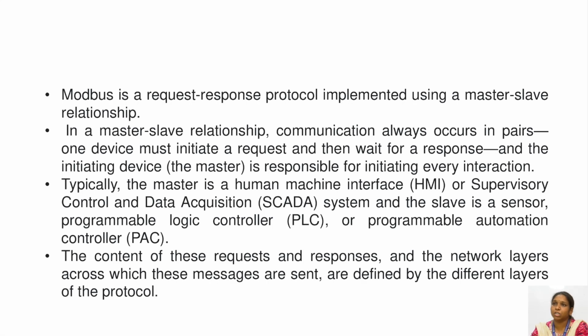Modbus is a request-response protocol implemented using a master-slave relationship. In a master-slave relationship, communication always occurs in pairs. One device must initiate a request and then wait for the response. The initiating device, that is the master, is responsible for initiating every interaction. Typically, the master is a human machine interface, HMI, or a SCADA system, and the slave is a sensor, PLC or PAC, programmable automation controller.